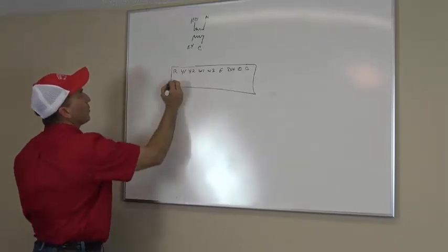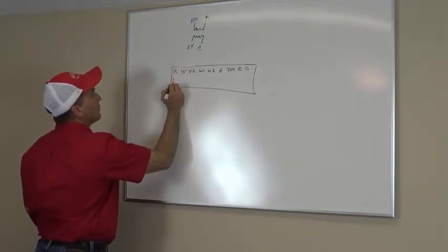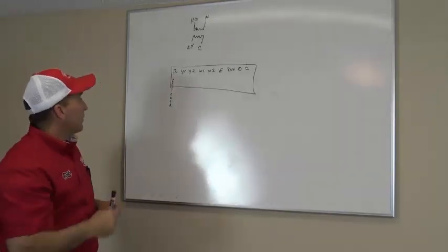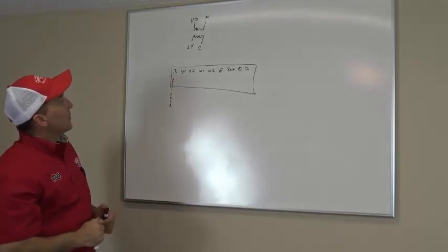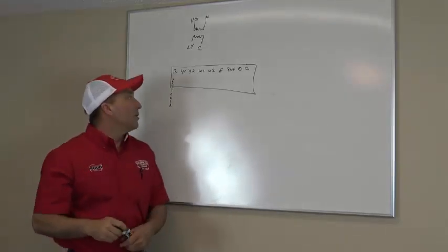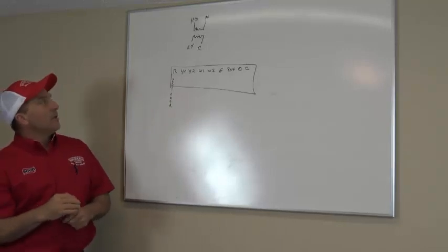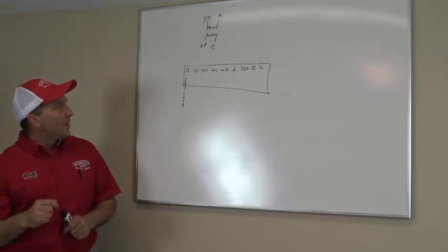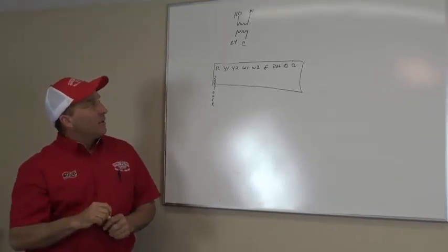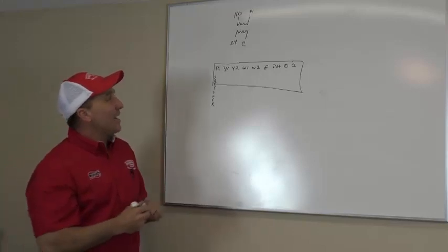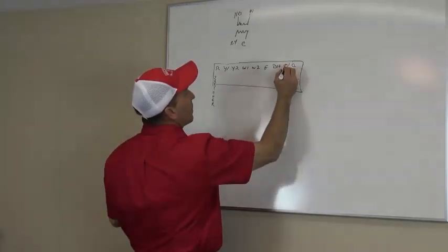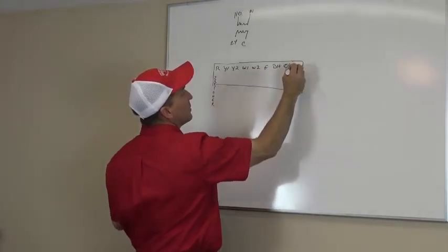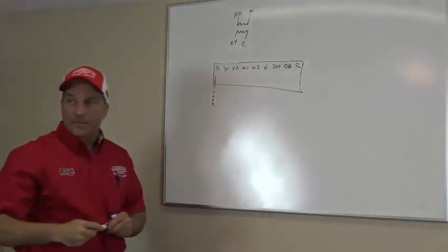Okay, 24 volts. Right? What's my Y1 for? First stage cooling. Y2, second stage cooling. W1, W2, first and second stage heat. G, fan. DH, dehumidification. O/B, reversing valve. And then your C is your common, right? Yeah. Okay.